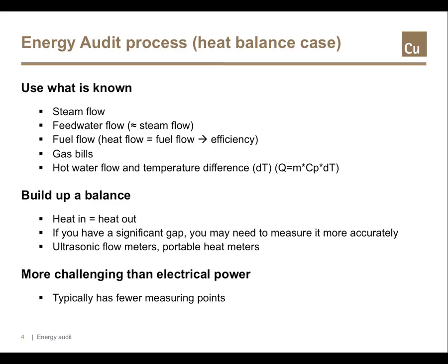Analysis using heat energy is more challenging than electricity energy, since typically there are fewer measurements available on site. If the energy auditor finds that there is insufficient data to carry out an analysis, measurements could be taken using ultrasonic flow meters, portable heat meters or other appropriate devices.